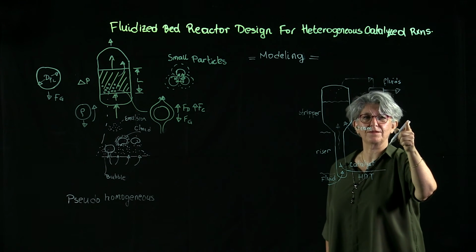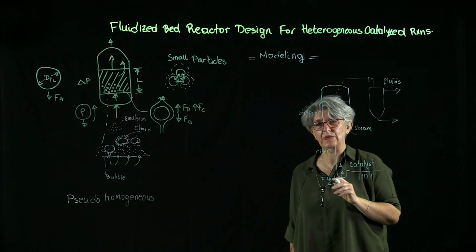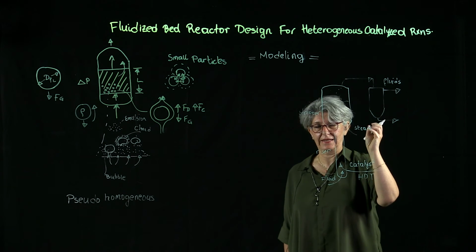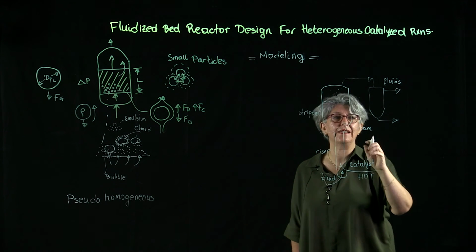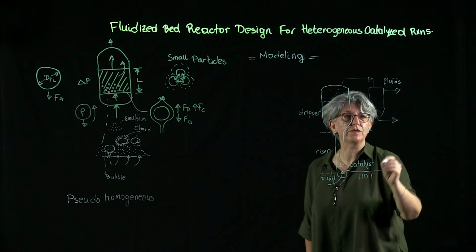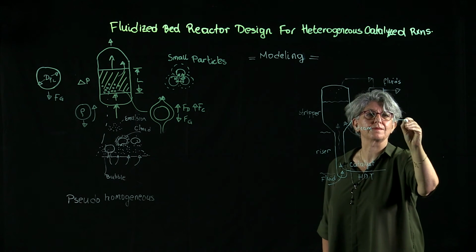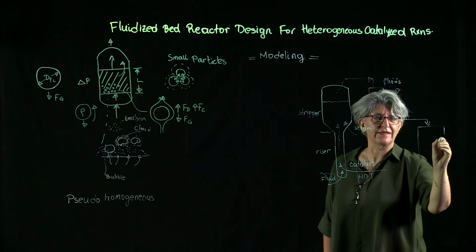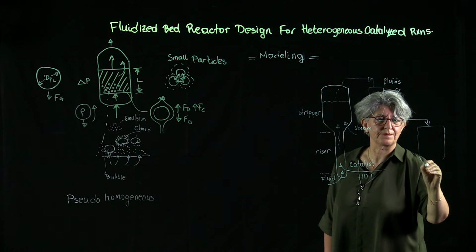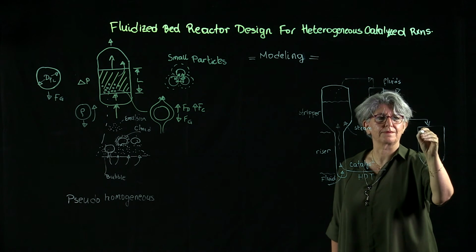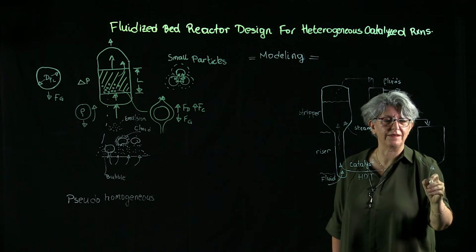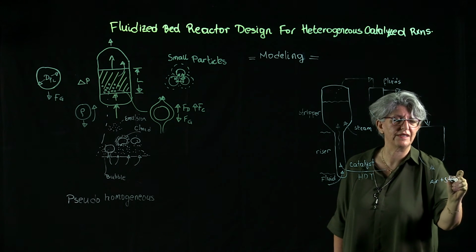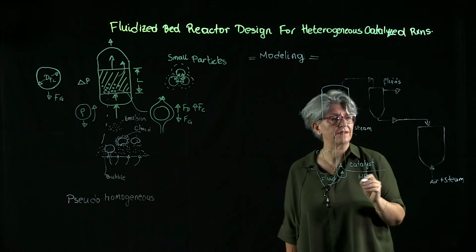We take the solids. What we have on the solids is a carbon layer which is deliberately, intentionally left on the catalyst, a carbon-coated catalyst, which is sent to another fluidized bed where we have this time air plus steam, depending upon the design of the reactor.